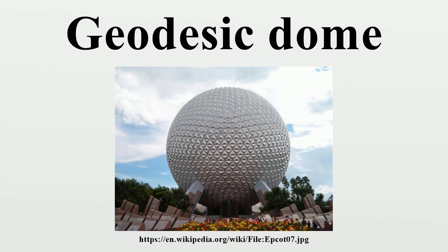Sounds, smells, and even reflected light tend to be conveyed through the entire structure. As with any curved shape, the dome produces wall areas that can be difficult to use and leaves some peripheral floor area with restricted use due to lack of headroom. Circular plan shapes lack the simple modularity provided by rectangles. Furnishers and fitters design for flat surfaces in mind. Placing a standard sofa against an exterior wall results in a crescent behind the sofa being wasted.